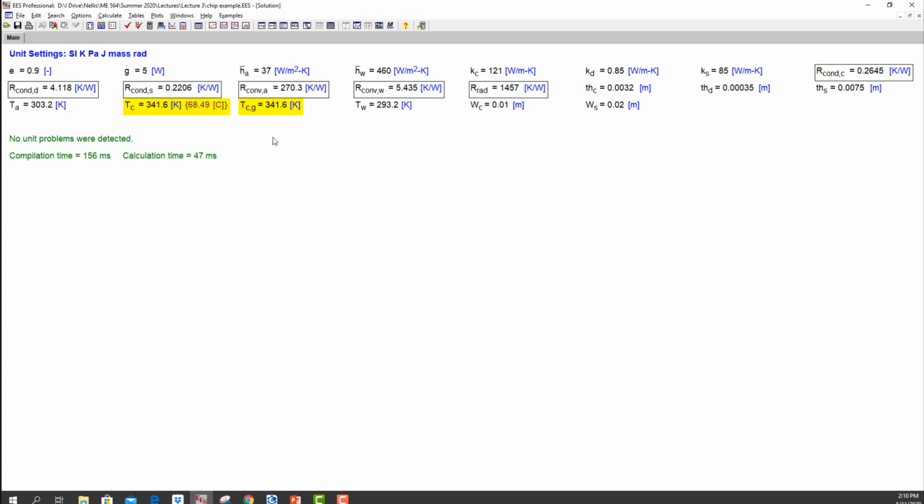So we actually just did something fairly complicated, and that was we solved a big set of coupled equations, right? And the reason that it worked without a hitch is that we started that solution process from a reasonable set of guess values and let it converge to the right solution. And that's a very useful trick when you're using EES. It's not even a trick, it's just a useful technique that you should get used to doing whenever you're using EES.